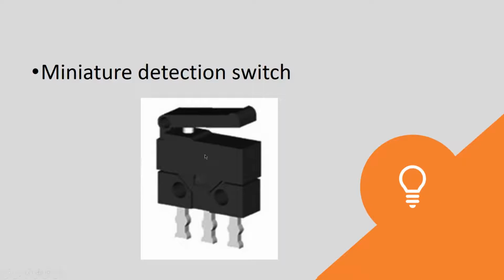This is usually used if you have ever heard about limit switches. When you have an object moving, usually in robotics or in CNC machines, you want to know that you have reached the end of the workpiece, or you have reached the end of the work area. And these switches are used so that the machine, like the control circuit, knows that the tool has reached the end, and it does not overlap to go to the other side, and it goes back within the defined range. So when you have a workpiece or a functionality whereby you want something to work within a confined region, these are the types of switches which are used.